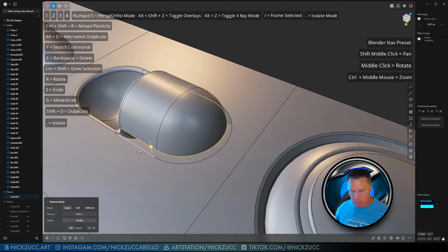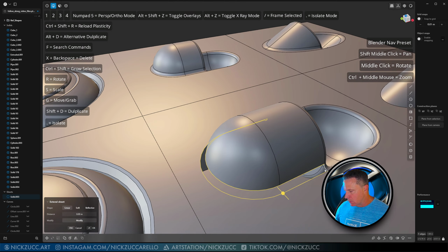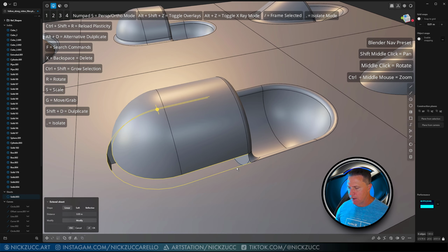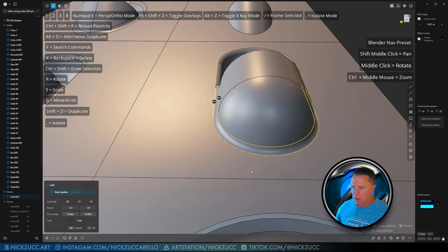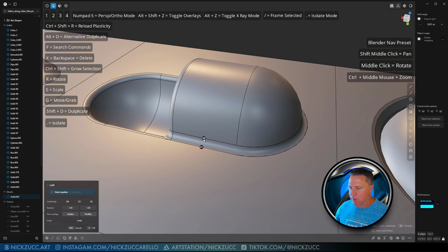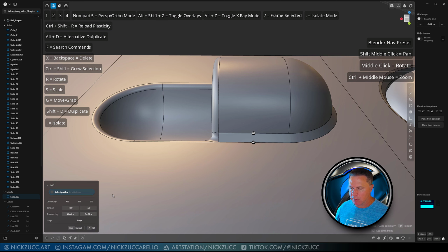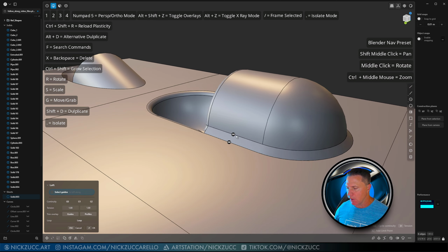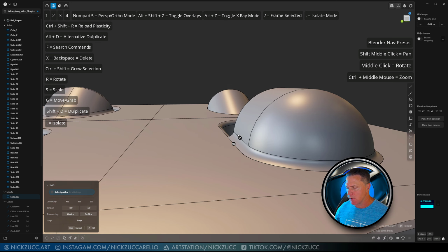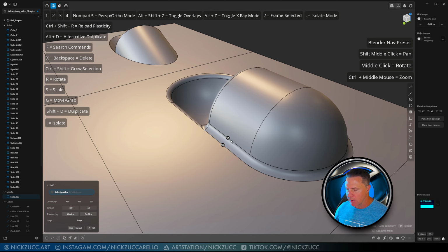So I'm going to hold down Alt here, like this, and click Control. I don't want this, and I don't want this. And so I'm going to just tap L for loft. And on here, instead of doing G1 for tangency, what I'm going to do is click G0 like this. And you can see that G0 will be purely hard edged on here. And then G1, if I click on that and change it to G1, you can see that this is going to be hard edge, and then this is still going to have a nice smooth transition.